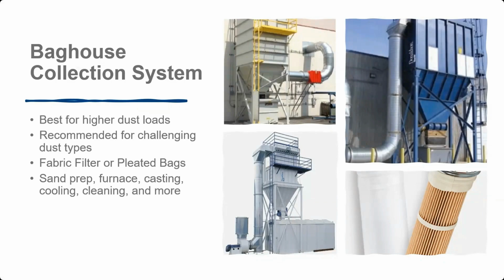The pulse jet dust collector cleans during operation, and you can make them a lot smaller and more compact, so they take up a lower footprint. I would guess to say 80% or more of the dust collectors in your facility are pulse jet dust collectors, so we'll be talking about these quite a bit today. They typically use a fabric bag in a cage, or they can also use pleated filters.